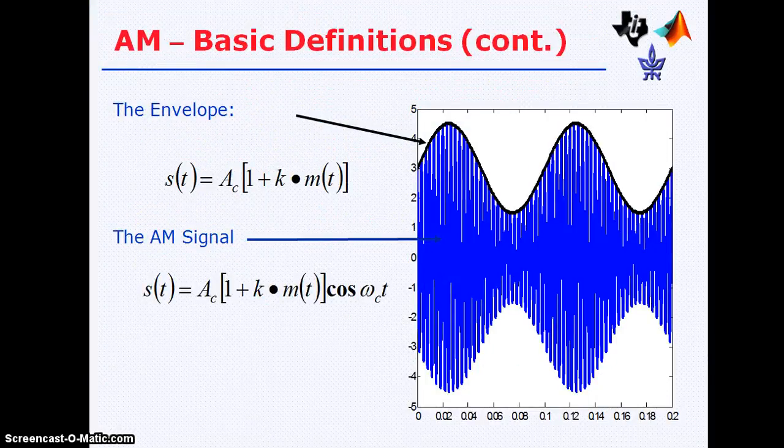In amplitude modulation, as can also be seen from this diagram, mathematically, if we decode this expression of s(t), we will get Ac cos omega c t plus m(t) cos omega c t. This is a mathematical term containing two trigonometrical terms, and if it is expanded, we can get a term with cos (omega c plus omega m) t, and one term with cos (omega c minus omega m) t.